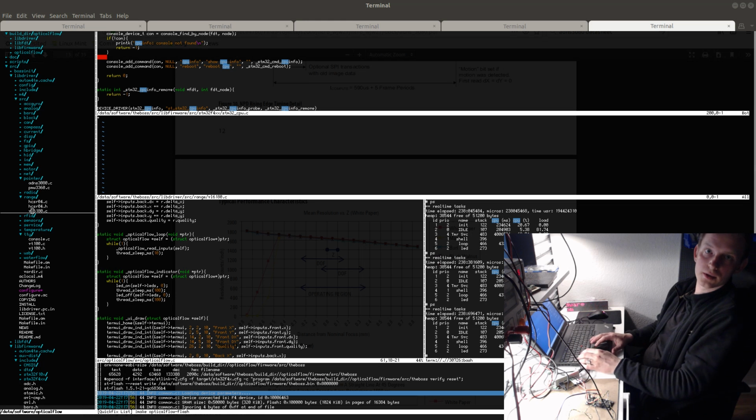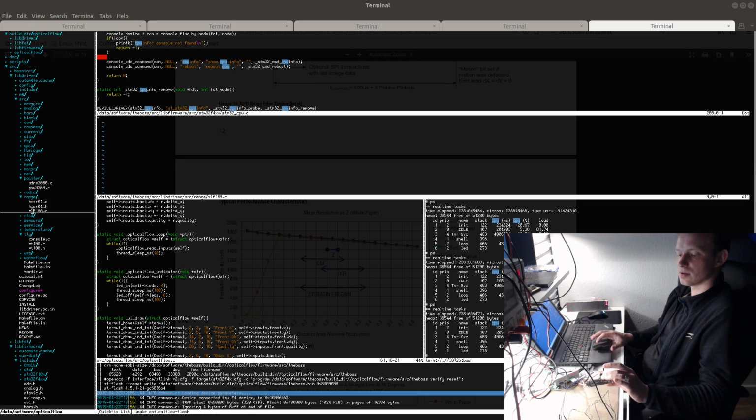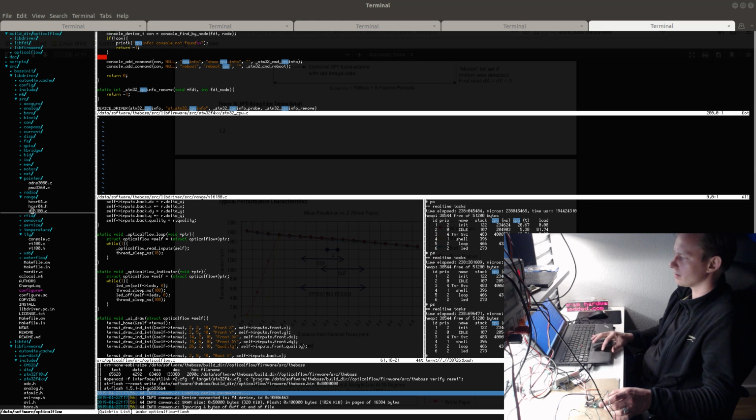Alright, in this video I'm going to start implementing support for the VL6180 laser time of flight sensor. I have placed 4 of these sensors on this little board here, and I don't even know if they work yet. I don't even know if they are possibly shorted because they're very tiny sensors, and the package actually melts if you increase the temperature past 260 degrees. We'll see how many of them work, if they work at all. Let's get to it, and let's get started implementing this driver in C on STM32.